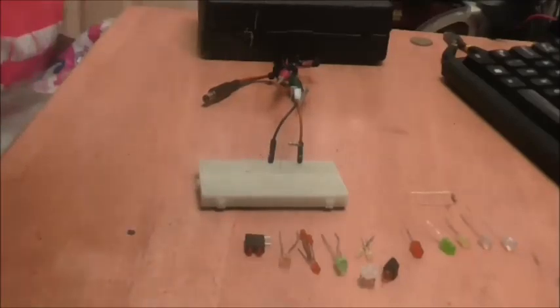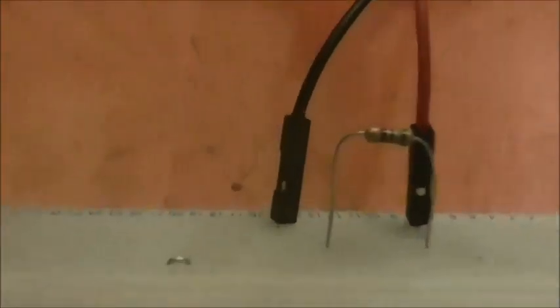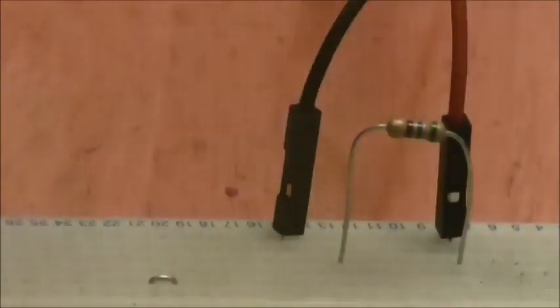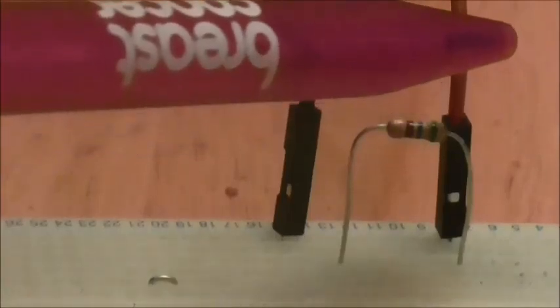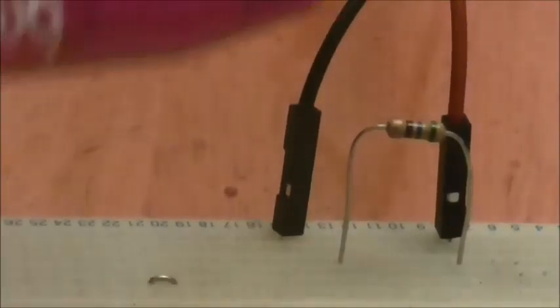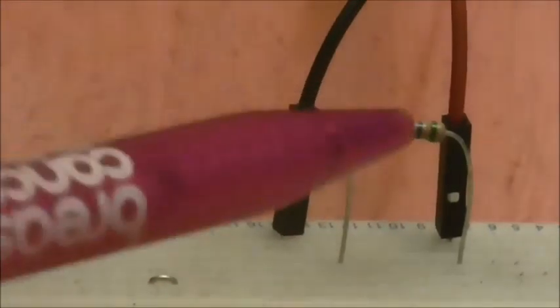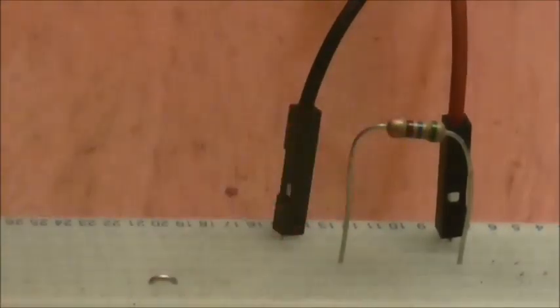And if I zoom in on the apparatus, you'll see that I've got a DC supply with a positive end, a negative end, and a resistor. The resistor here is 540 ohms, and as you get a bit older and a bit more experience with these things, you start to find shortcuts, and my shortcut is that with 5mm LEDs and on 9 volts or less, I can use a 540 ohm resistor for any LED and it will work properly. And if I want it to be a bit brighter, I use a 330.